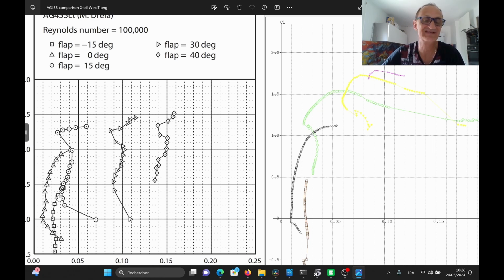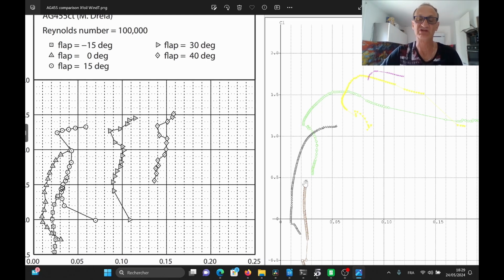The drag is still underestimated when you are starting to push the limit, which means that you start to have more incidence. But that's really interesting because you are better off having some negative flap during a turn rather than having positive flap during a turn.